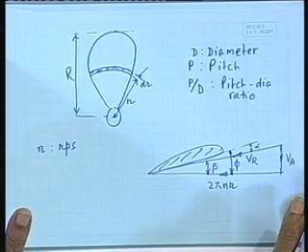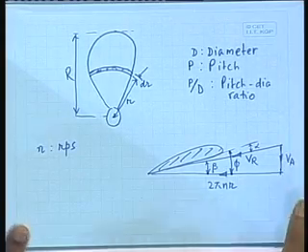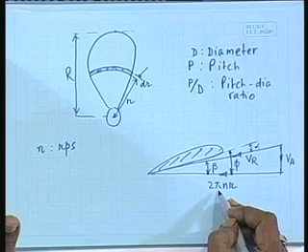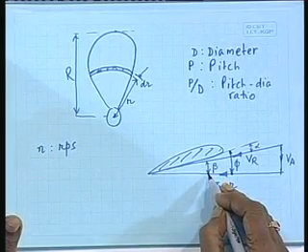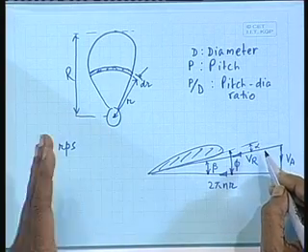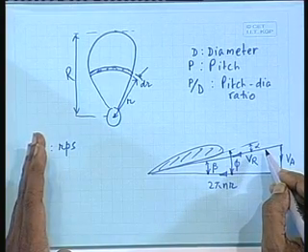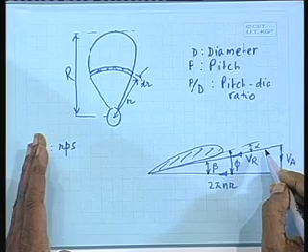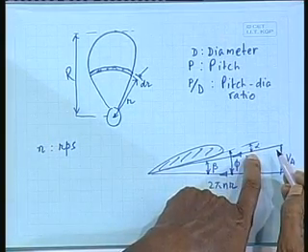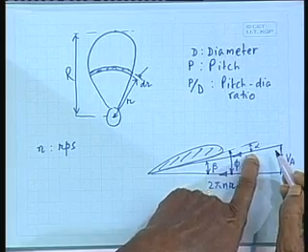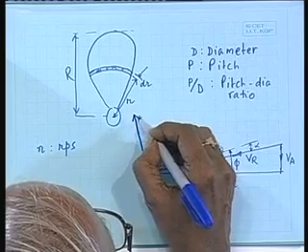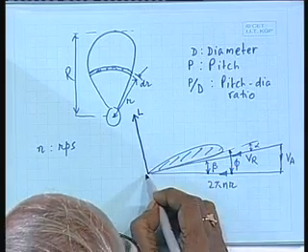Have you understood? That means, if we know the axial velocity and the tangential velocity, then we can calculate beta, and we can also see what is the geometric angle of attack. Is that clear? So, now lift and drag will depend on this angle of attack, right. So, lift will be here and drag will be